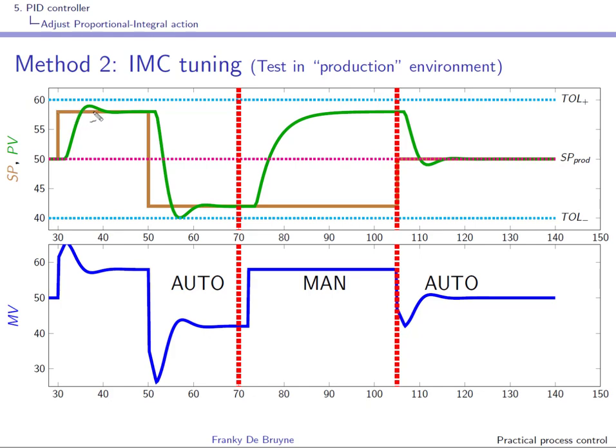The reason why you do this set point change is because in steady state you will have the corresponding steady state value of MV, and this you will need when you're doing your open loop step response.